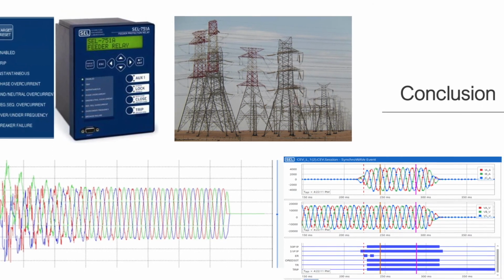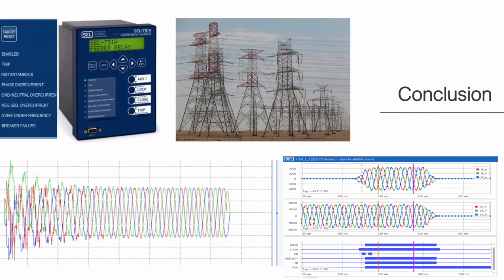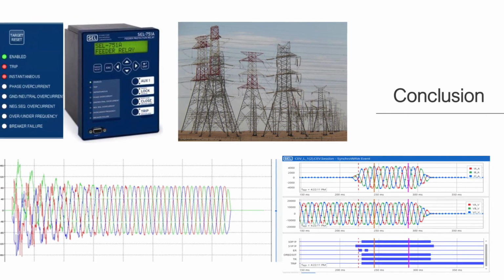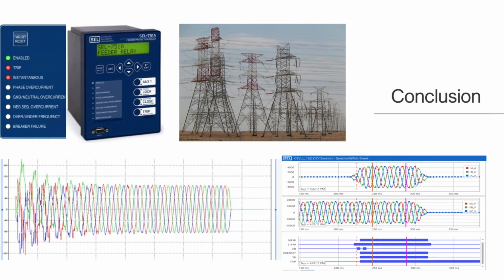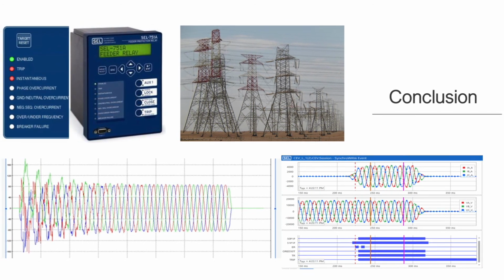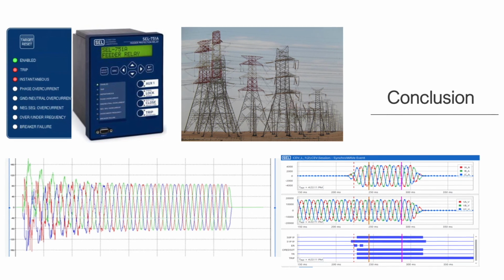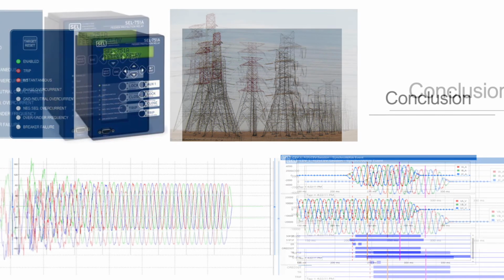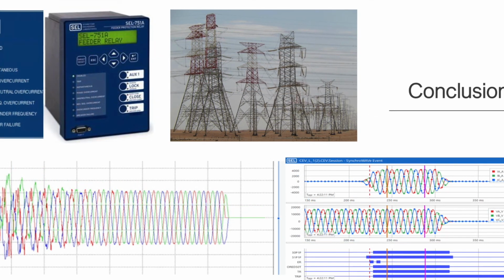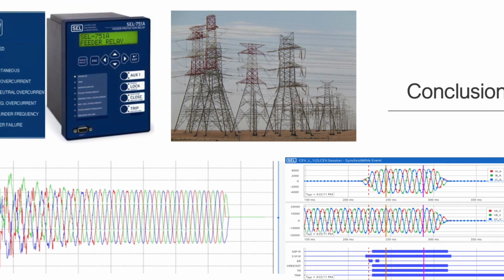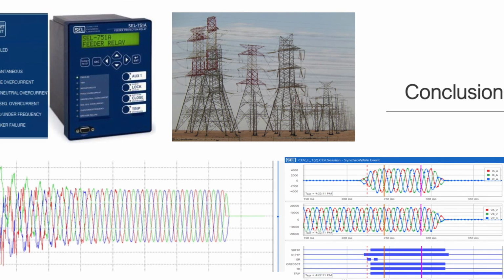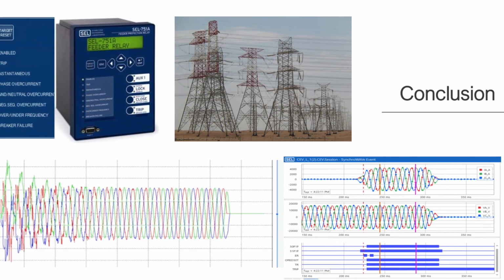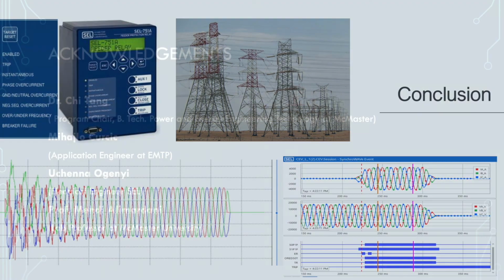The overcurrent fault analysis is done using Scope View and Synchrowave. It is observed that the fault current is much higher than the load current. The SEL-5401 uploaded the overcurrent fault on the 751 relay. The relay has settings for tripping time and time dial. When the relay sees the overcurrent fault in the transmission line, it trips to clear the fault. Overcurrent causes overheating in the transmission line and leads to short circuit. The project is successfully completed and the scope of the project is obtained.